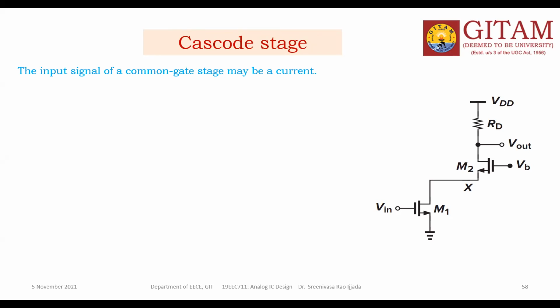With the single stage amplifiers, single stage transistors, we could not achieve our requirement fully. So our targeted achievements are difficult to get from the single stage. So now we should go for multiple stages based on the requirement. Mostly we are talking about the gain. So gain of the single stage MOSFET is very small. We cannot satisfy the requirements of the design fully. So mostly MOSFETs may be cascaded and cascoded. Two configurations are there to increase the gain.